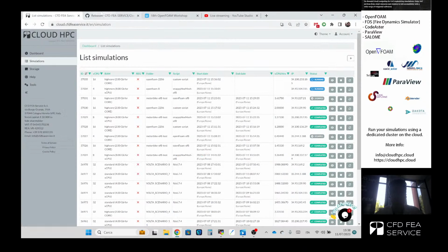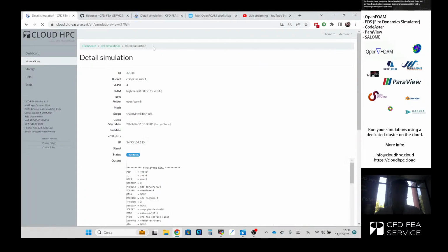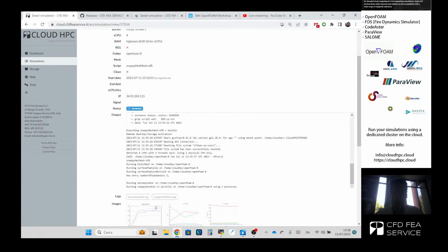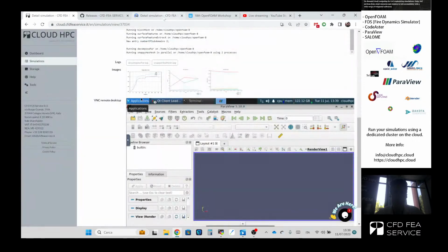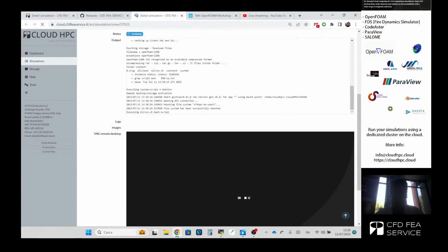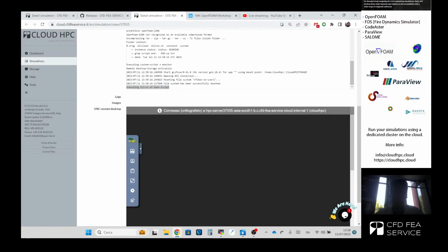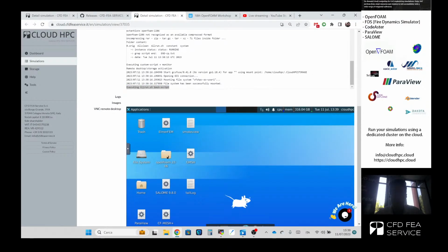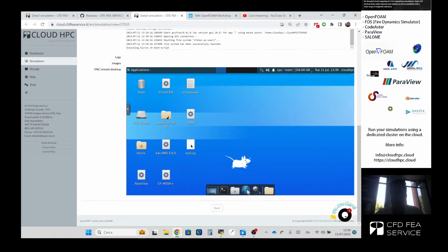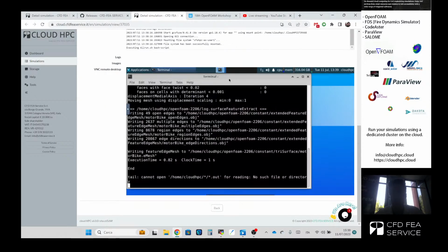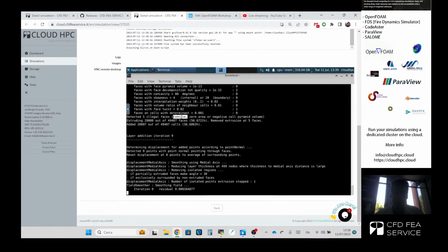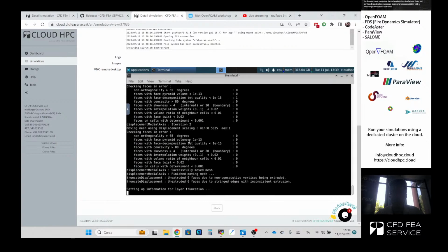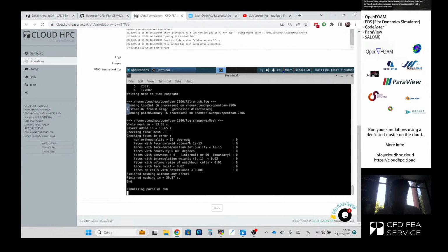So we just go back here to see what is the status of our analysis, and then with this tutorial probably it's over. So Snappy is still in the phase of generating a mesh, and instead in here you see all run is now in execution. It says executing the Allrun.sh bash script. So in here, if I double click on tail log, I can actually see the script Allrun probably is in the SnappyHexMesh generation of the mesh itself.